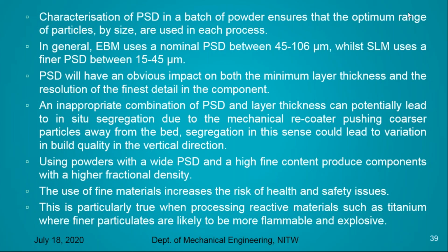Generally for the EBM process, we are using a particle distribution of 45 to 106 micron, and for the SLM process we are using, as I told you, 5 to 45 micron as well as 15 to 45 micron, depending on which machine we are using. This particle size distribution will have an obvious impact on both the minimum layer thickness and the resolution of the finest detail in the component. Which finest detail we can get in the component depends on the particle distribution.